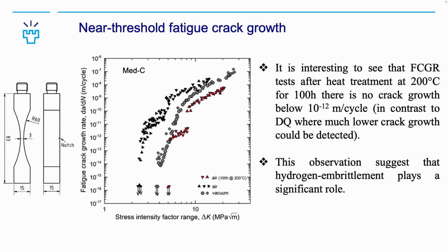Further, when we did the additional tempering treatment, we see further improvement. Actually, there are two phenomena that may be associated during this tempering. One is dislocation annihilation, causing the improvement of the fatigue crack propagation. Another one would be the hydrogen, which is trapped inside the materials during the processing time. During tempering, maybe some of the hydrogen is released, and that causes this improvement.